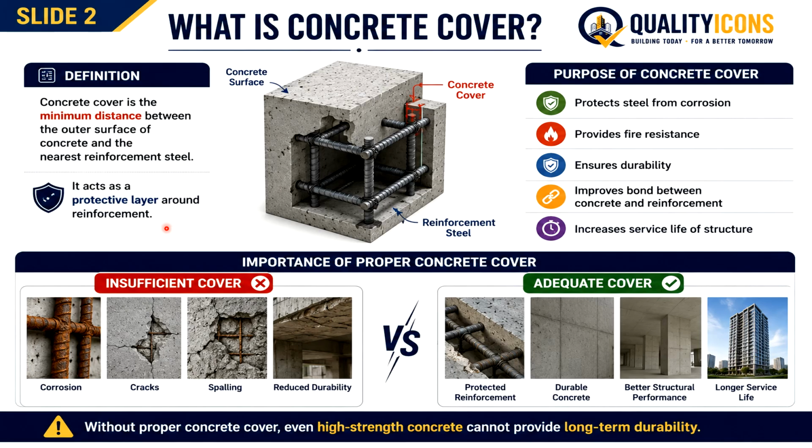Concrete cover has five important functions. First, it protects reinforcement from corrosion. Second, it provides fire resistance. Third, it improves durability. Fourth, it creates a strong bond between concrete and steel. Finally, it increases the service life of the structure.